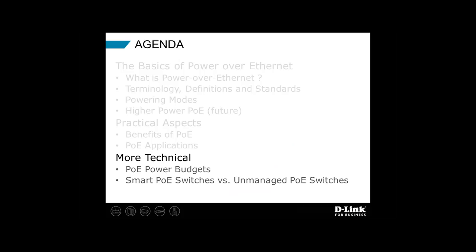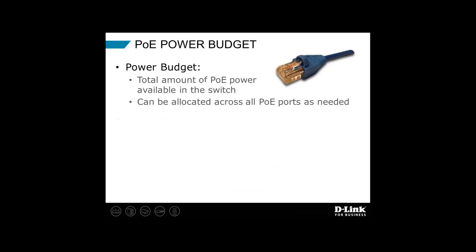Good. I'm going to go into the last section here just quickly and talk a little bit about PoE power budgets and then talk about smart PoE switches. PoE power budget is pretty simple actually. It's the total amount of PoE power available in a PoE switch. And this power can be allocated across all PoE ports as needed.